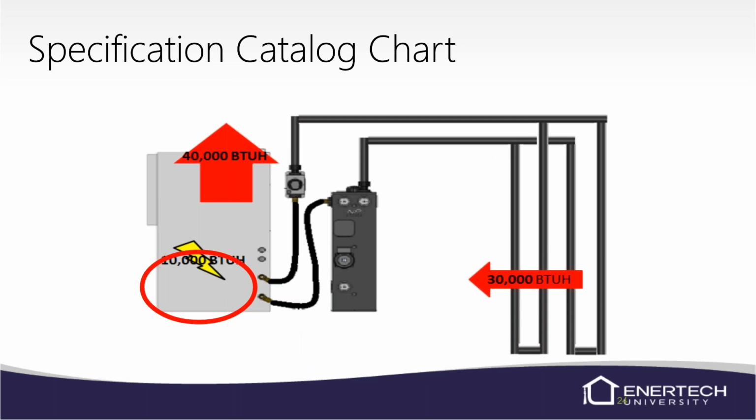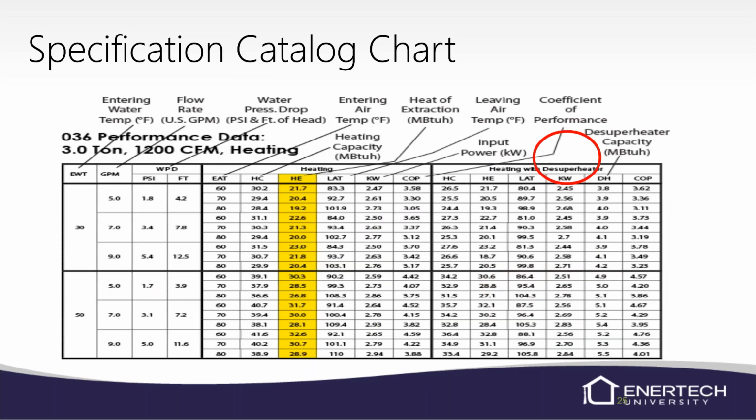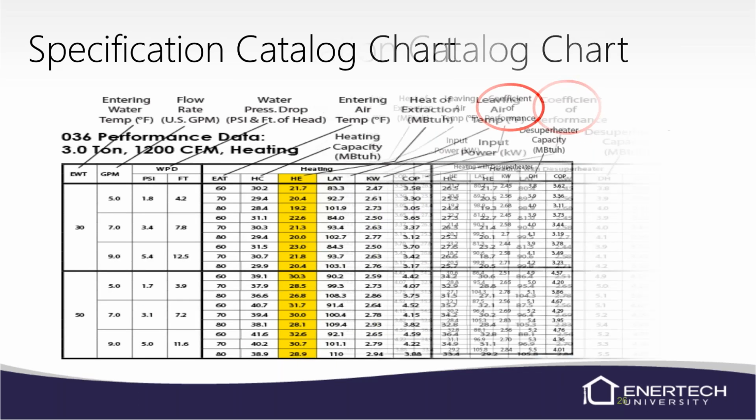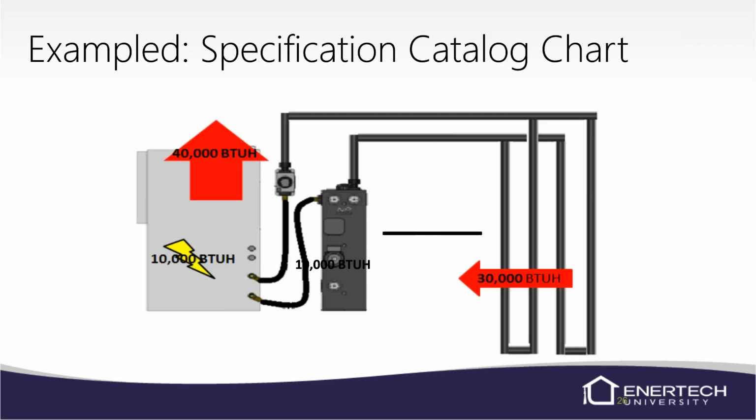And then basically with COP, the calculation for it is BTUs delivered divided by BTUs supplied. So the BTUs supplied to create this process is 10,000 BTUs. That's the number we figured out with our amps and volts.